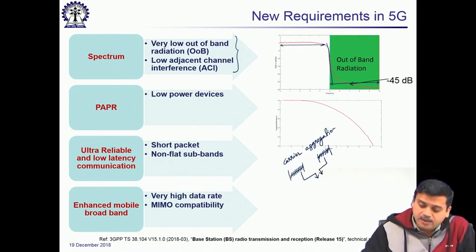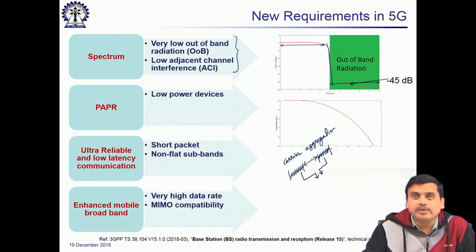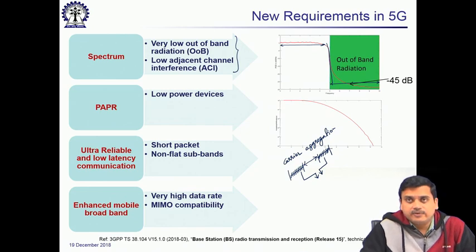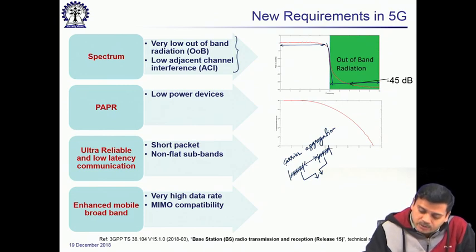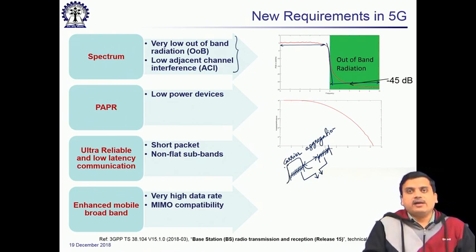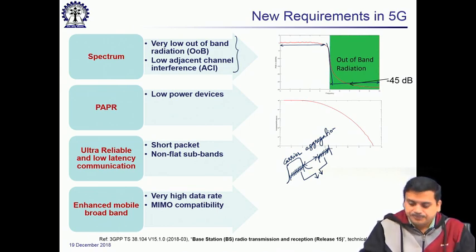This is one thing. But now look at the other side of the same picture: there are some bands which remain in between. This is very critical. So, if one has to utilize all the bands in the most efficient manner, one should have spectrum properties of multi-carrier signals which are expected to be as close to Nyquist filter characteristics as possible. That is what is desired. In that case, one can utilize things better.